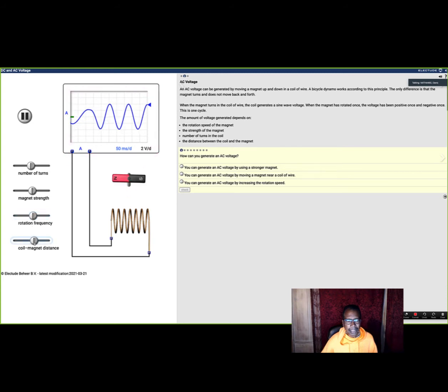And here, the gap gets closer. Look at the signal. Somebody set the gap, like on a crank sensor or a cam sensor, too wide. Now look at the signal. I went the wrong way, the opposite direction. That's closer. This is further apart.